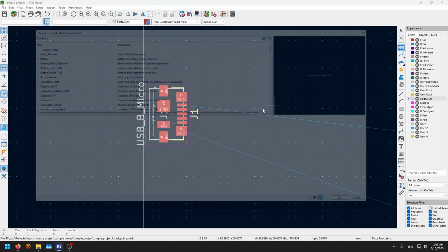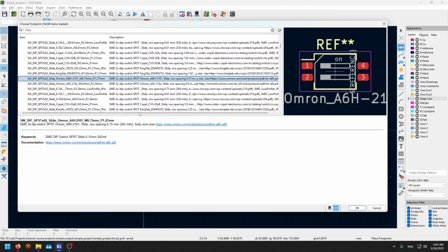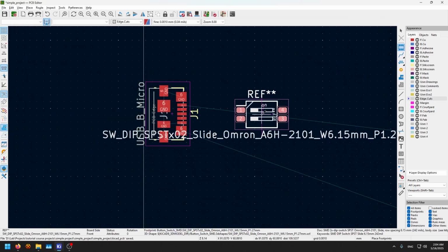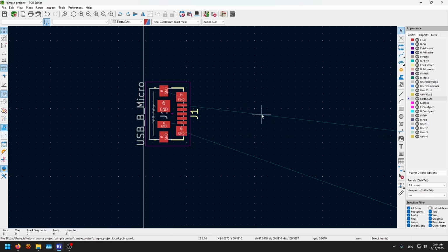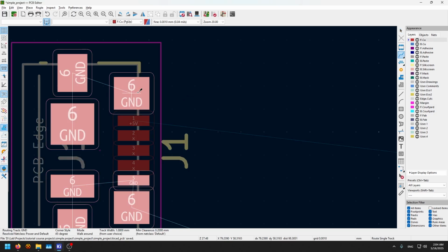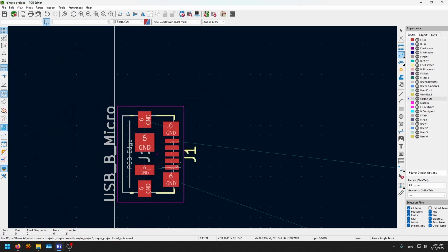This one adds a footprint similar to the library thing. Select for any footprint that you want and basically okay, and you're gonna add it, but it's not gonna be associated with a schematic symbol, and I don't recommend this. Everything must be linked with the schematic. This is the routing tool. Basically I'm gonna either press X for this pad and start routing, or basically press here and select the pad that you want and basically start routing.